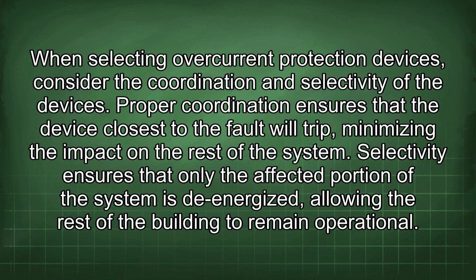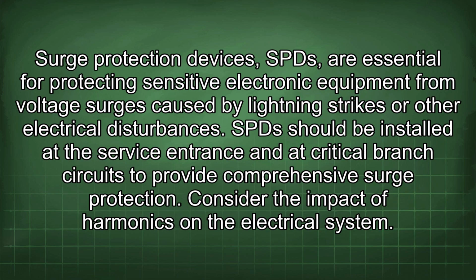Surge protection devices, SPDs, are essential for protecting sensitive electronic equipment from voltage surges caused by lightning strikes or other electrical disturbances. SPDs should be installed at the service entrance and at critical branch circuits to provide comprehensive surge protection. Consider the impact of harmonics on the electrical system.